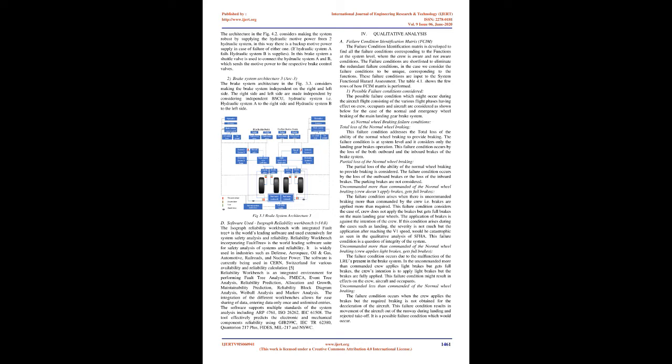Design of the two architectures, Architecture 2 and 3, for the brake system of the main landing gear. The following two architectures, Fig 3.2 and Fig 4.3, have been constructed for performing the sensitivity analysis, to realize how the safety changes, or to understand how sensitive the architecture of the system is for safety.